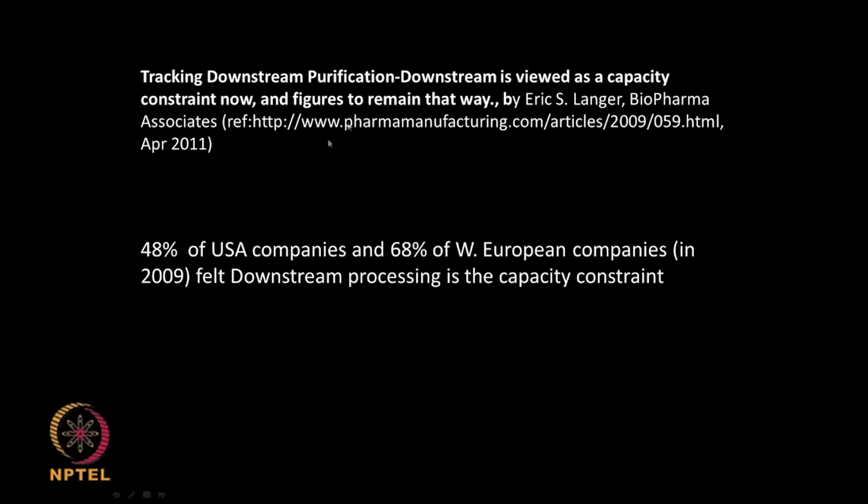Okay. So if you look at some reports, it says 48% of USA companies and 68% of Western European companies feel that downstream processing is the capacity constraint. That means it is easy to add one more fermenter, it is easy to add one more bioreactor if I want to expand my process, but then the downstream is going to be really constraining, and it is not so easy just adding a few chromatography or separating equipment. So that is going to be your real bottleneck.